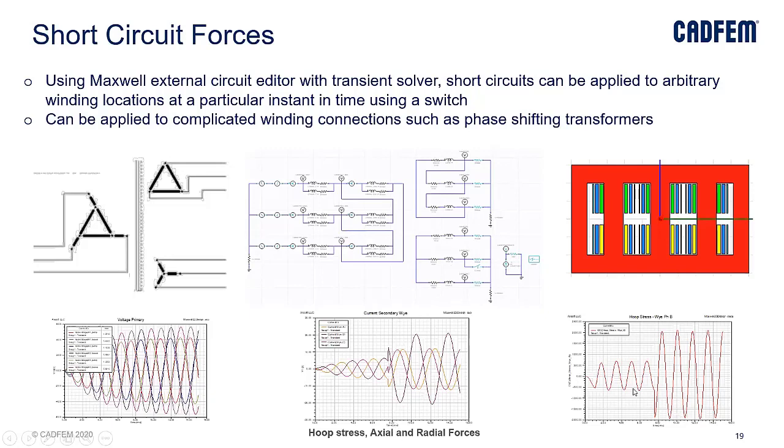and this is going to be short circuited at a point of 8 milliseconds. You can see how the stress levels have increased. Due to these stresses, there are axial and radial forces acting on these windings. This kind of thing can be easily tested virtually, and we can cross check whether our design can withstand it or not, which will help us pass the physical test. Of course, we cannot avoid the physical testing, but repetitive physical testing can be avoided, without any misfire in the physical testing. And over to Thanakorn. Thank you, Hara.